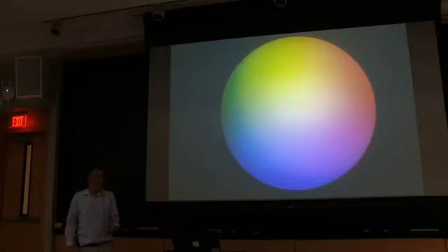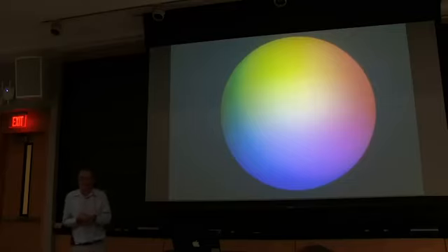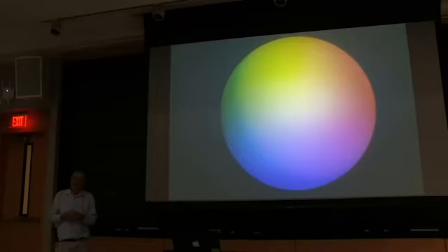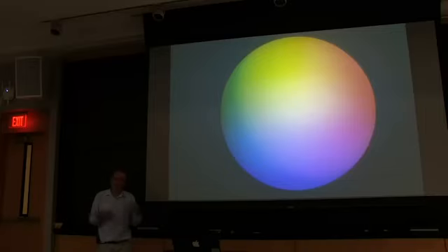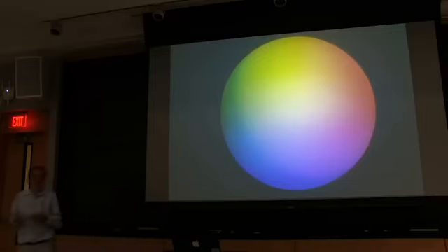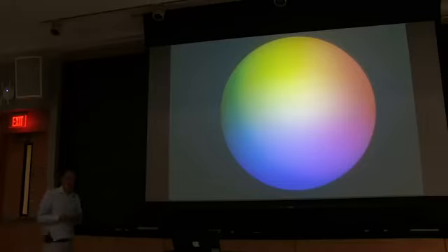Another way to look at it is that a pixel is small. How big is a pixel in a typical camera? We can sort of figure it out. The chip is a few millimeters by a few millimeters, and we have a few thousand columns and rows. So it's a few microns. There are huge trade-offs: the one in your phone has smaller pixels, the one in a DSLR has larger pixels. But in any case, they're tiny.